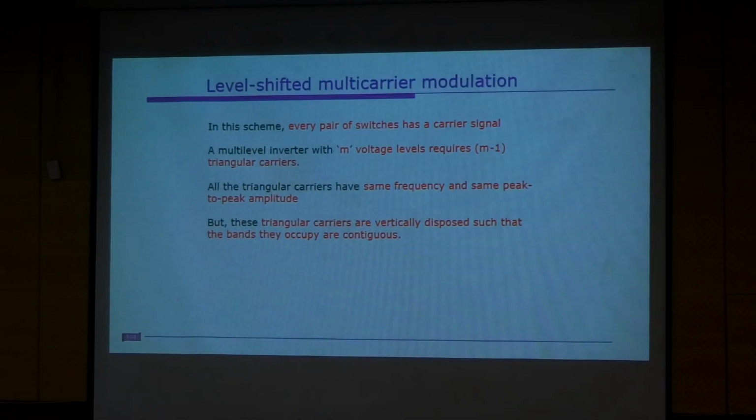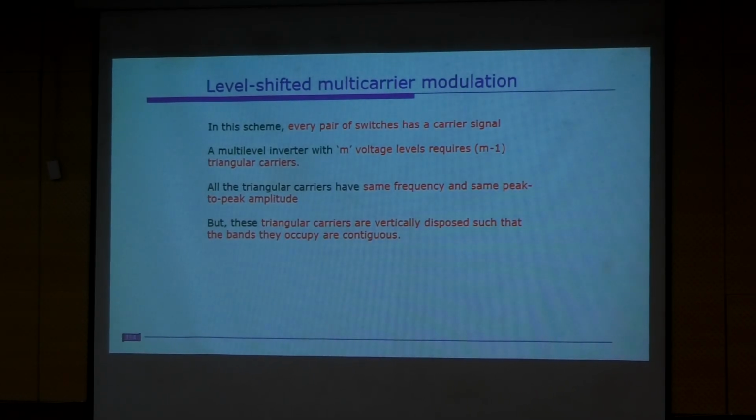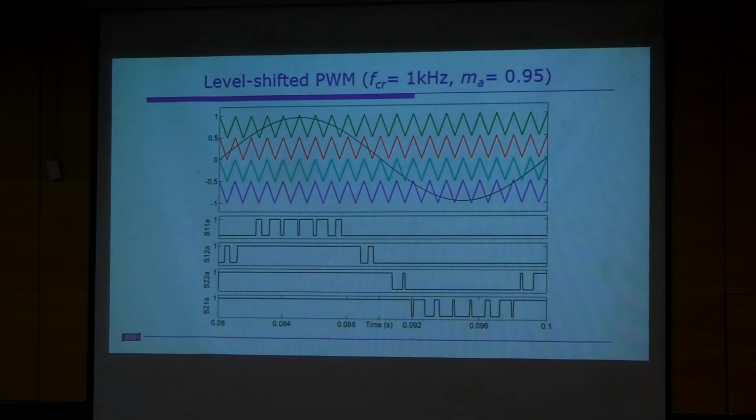This is the level shifted PWM technique. It is just straightforward. Same thing: we have m number of levels, so m minus 1 number of carriers. But instead of the earlier arrangement, these carriers are vertically disposed. This is how these carriers are arranged.